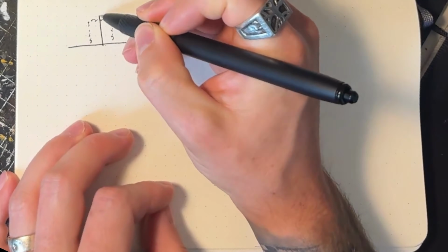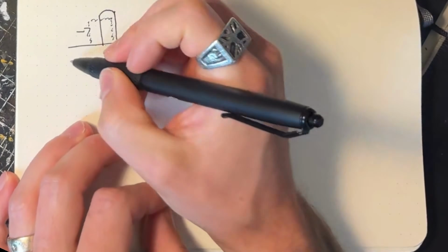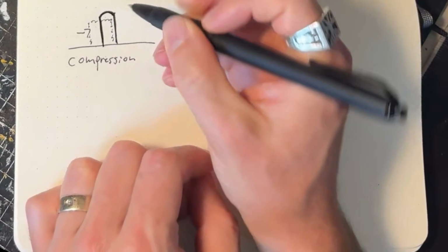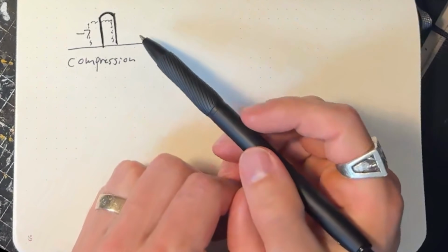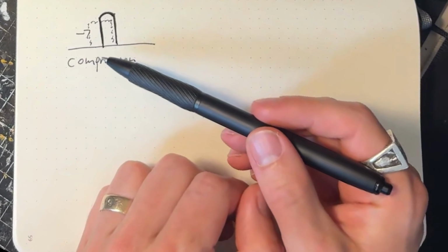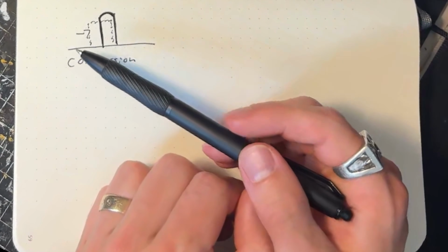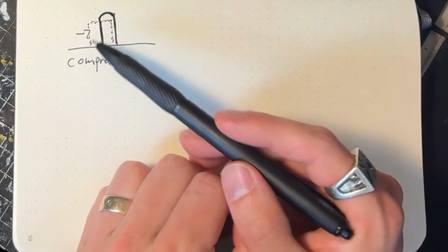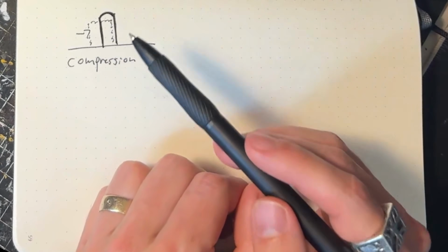Now, the third outcome is that the object itself actually changes shape. And there's six really common ways that an object can change shape. And in most cases, engineers design things so they don't change shape. But sometimes you design things so that they do intentionally. And the first type of force is something called compression. So we've kind of squished up and made our object a little bit more compressed inside of the space that we were originally given. You can think of this kind of like a car's crumple zone. It's designed to compress during that collision. And by deforming, it absorbs a lot of that energy from that crash and protects those passengers that are inside. It's a change in shape by design.